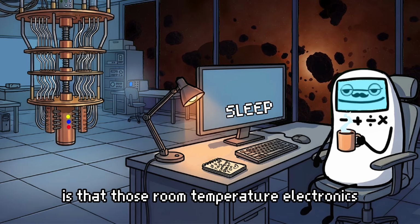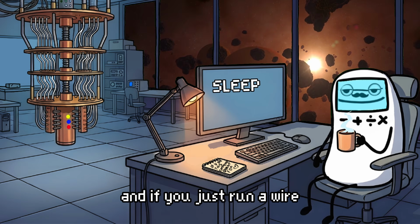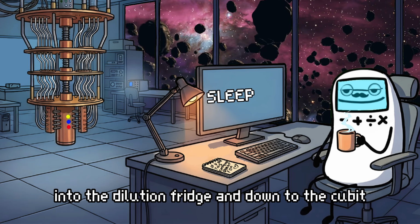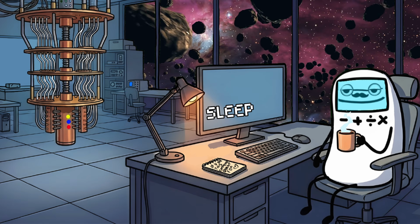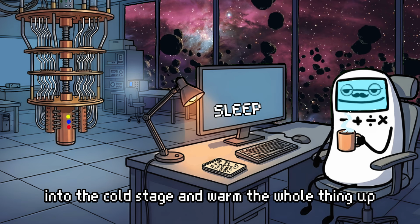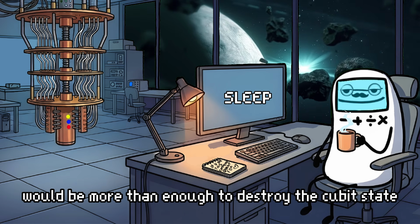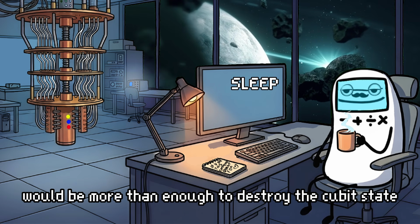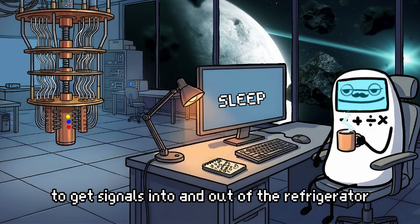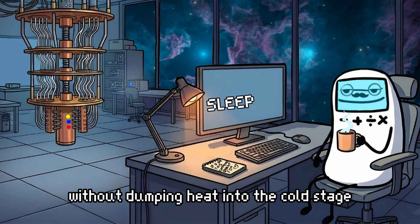And the problem is that those room temperature electronics generate a lot of thermal noise. And if you just run a wire directly from your room temperature signal generator into the dilution fridge and down to the qubit, you'll pump enormous amounts of heat into the cold stage and warm the whole thing up. And even if you didn't warm it up, the thermal noise on that wire would be more than enough to destroy the qubit state. So you need a very sophisticated wiring strategy to get signals into and out of the refrigerator without dumping heat into the cold stage.